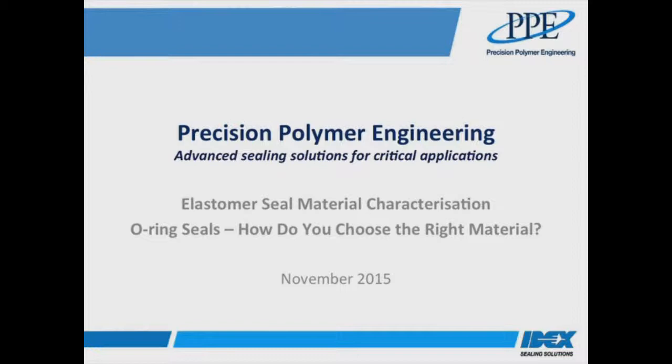So in today's presentation, entitled O-Ring Seals, How Do You Choose the Right Materials?, I will be focusing more on dry, or the more common plasma processing applications, and the effect of various process chemistries on a wide variety of different elastomer materials.